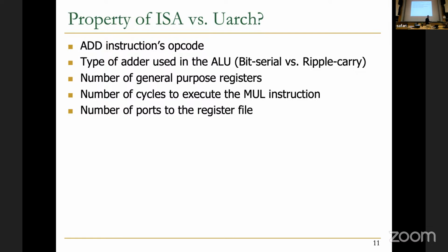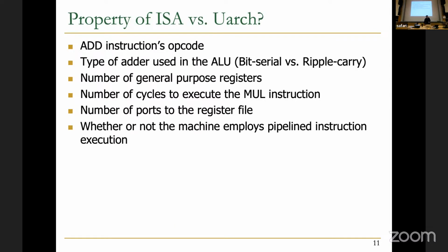The register file is an architectural concept, yes, but how you access it is implementation. The architectural concept just specifies what you do to the registers. It doesn't specify how you should do it. You can read the registers serially. You can have 10,000 ports to the register file and use one of them, right? Or you can have only one port to the register file and read it multiple times to get multiple values, right?